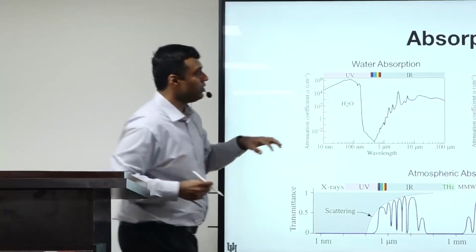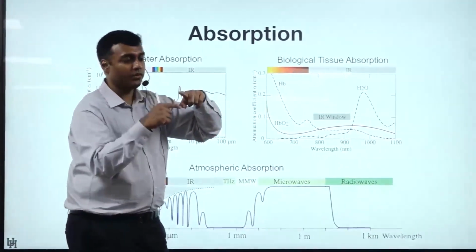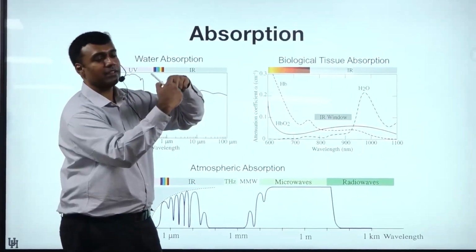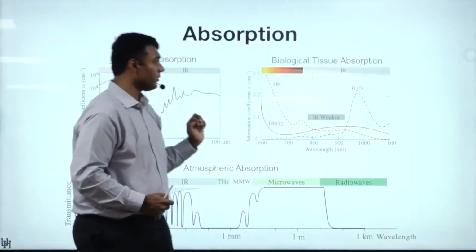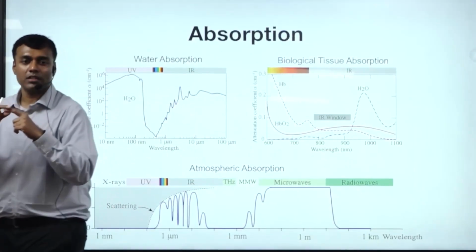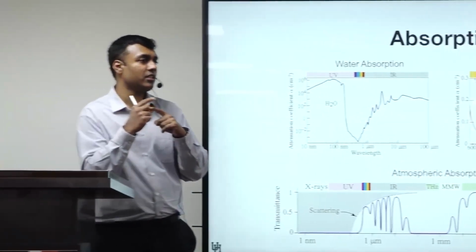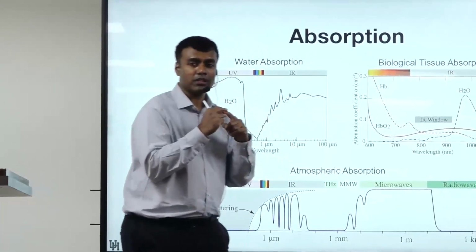It uses the fact that light goes through the finger. There is a light source here and a detector here, and you make measurements at two different wavelengths. It turns out that this tells you how much oxygen there is in the blood. It's one of the things it can measure: blood oxygen saturation.